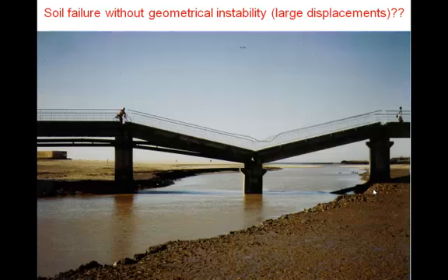Interesting to contemplate is what sort of limit state is this? Clearly the pier has settled an enormous amount. The bridge apparently is still in use, so maybe it's still serviceable. I think most people would regard that as an ultimate limit state. It's reached a dangerous situation.